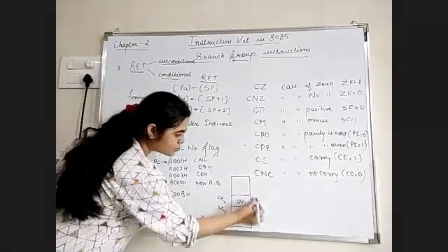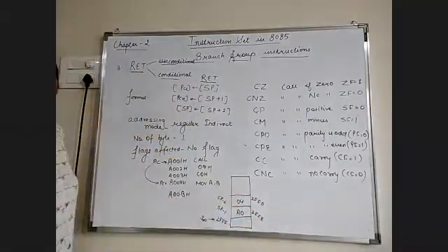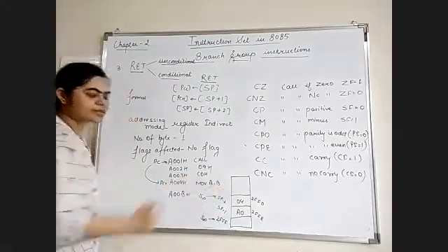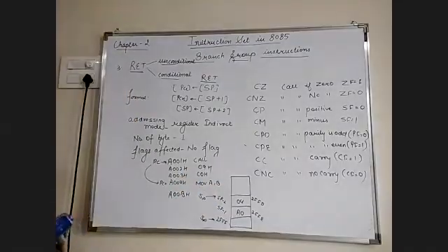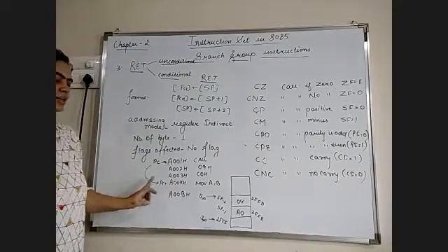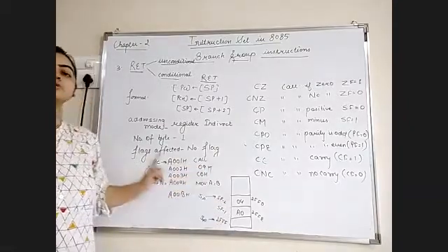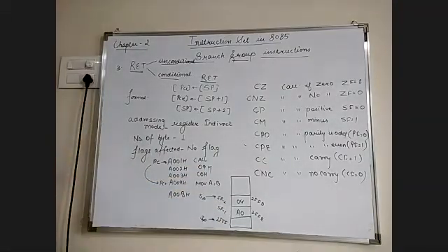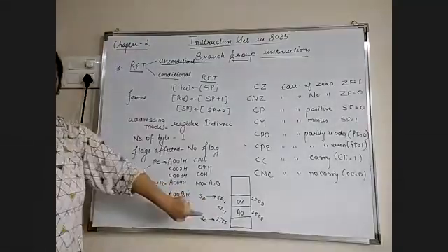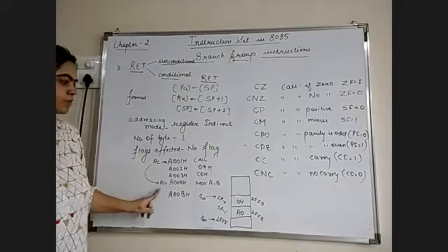So this is 2FFDH and this is 2FFEH. After pushing the contents, the stack pointer now has a new address, that is 2FFDH. This is part of the calling statement, because in case of a calling statement we push the contents of the memory location of the next instruction into the stack memory.